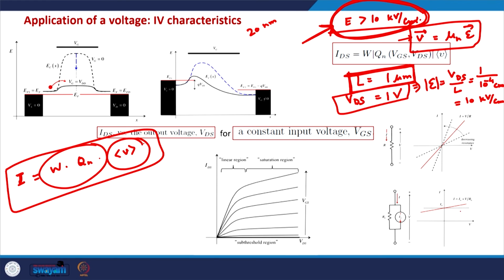Okay. So these are two reasons of saturation. One is the pinch off and second is velocity saturation. But there is an interesting nuanced point here, in very small channel MOSFETs.